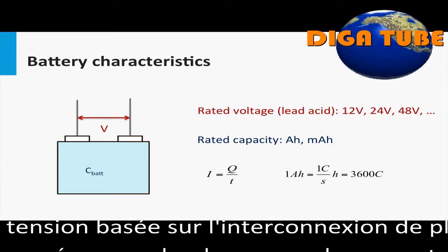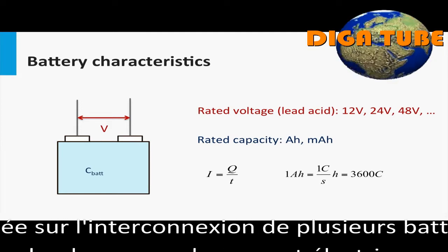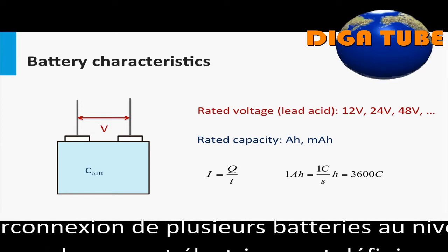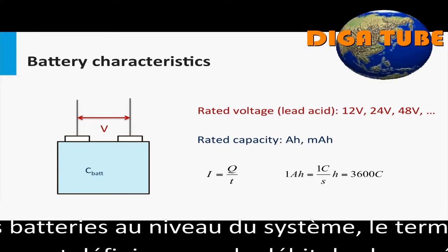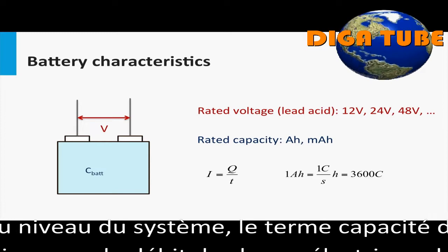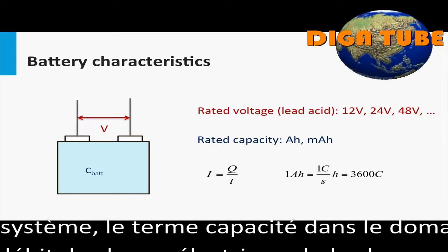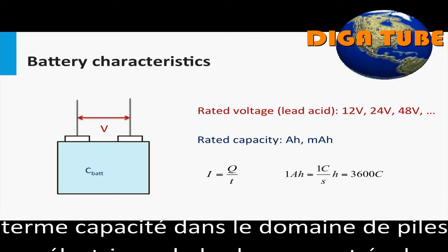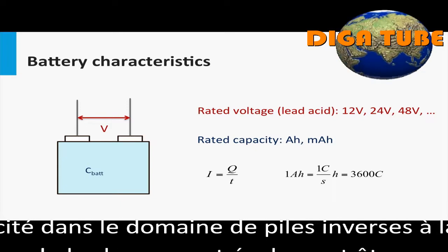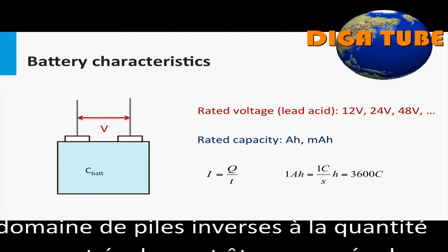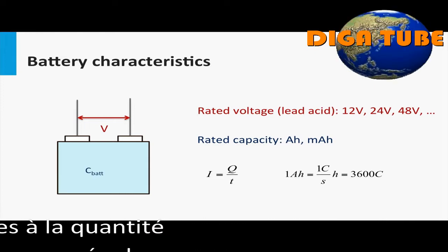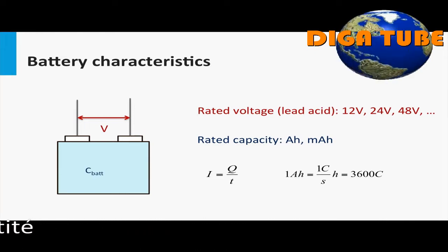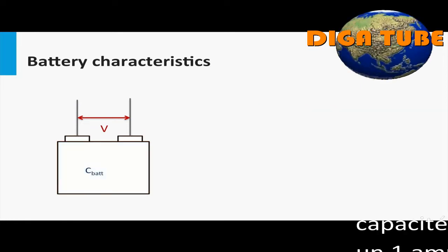As the electric current is defined as the rate of flow of electric charge, the charge can also be equivalently measured in ampere hour. Therefore, we can quantify charge in both coulombs or amp hours. But we will stick to the more convenient unit of amp hours for measuring the battery capacity. I will shortly explain the reason for this.